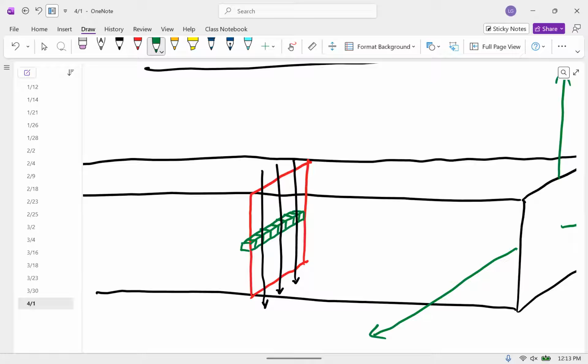Yep. So if you think about it that way, it makes perfect sense that the stress due to a shear force is an xy shear stress. Okay, it's on the x face, and it's actually in the negative y. So a positive shear force produces a negative xy shear stress.